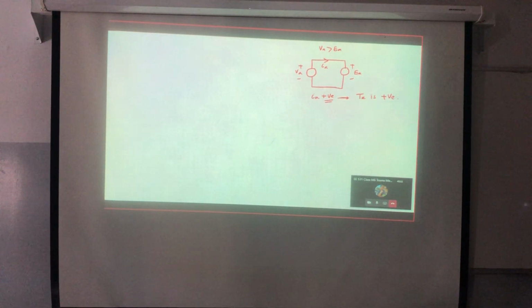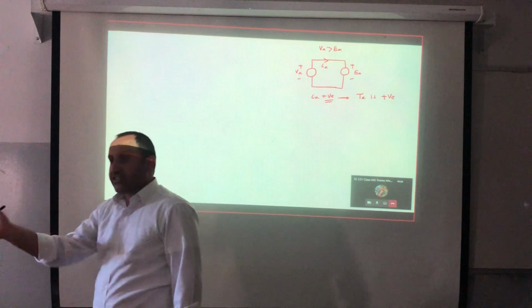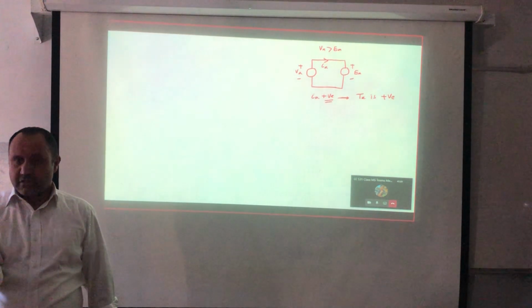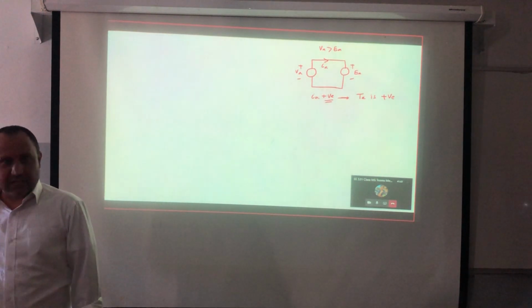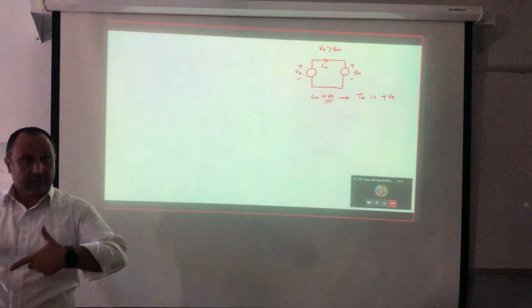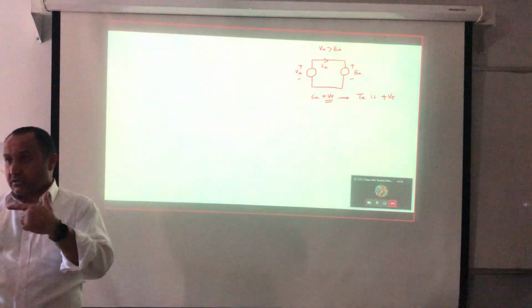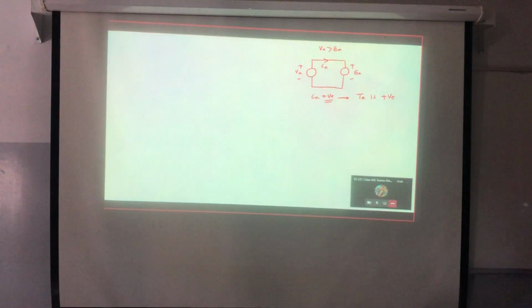Positive sign. Why? Because by assumption I'm fixing the field. If the field is changed, I cannot say anything. I cannot discuss the operating mode, because maybe the forward will be reversed. You know that I can reverse the direction of rotation either by changing the field direction or the armature direction. Correct? Good. Now, is EA positive or negative? From the plot, EA is positive, so this means that omega is positive.